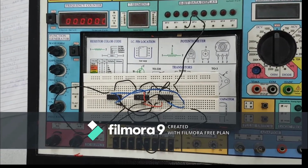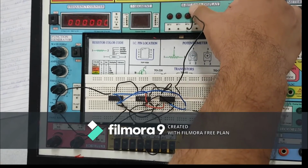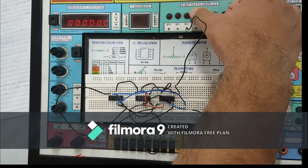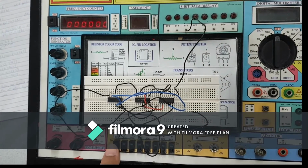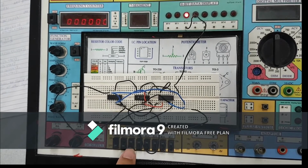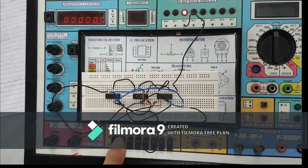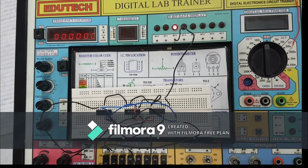According to our truth table, we should get an output that is shown by this light bulb lighting up. This light bulb will light up if it's 1, and it will not light up if it's 0. We should only get an output 1 for A and B equals 1 and C equals 0. For other inputs, as you can see here, we will get a 0 output, except for A and B equals 1 and C equals 0.